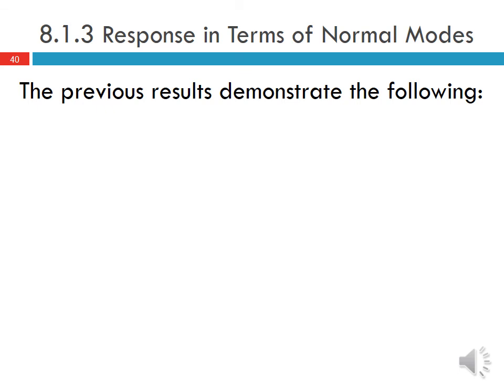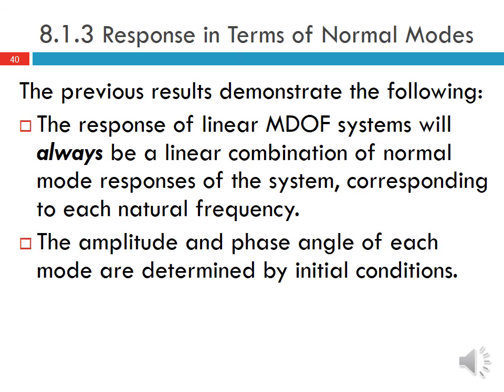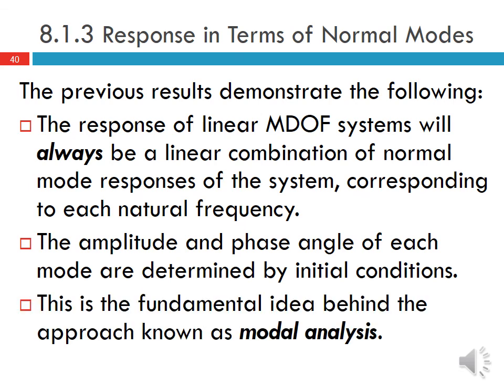So the previous results demonstrate that the response of linear multiple degree of freedom systems will always be a linear combination of normal mode responses of the system corresponding to each natural frequency. The amplitude and phase angle of each mode are determined by the initial conditions. So this is the fundamental idea behind the approach known as modal analysis.